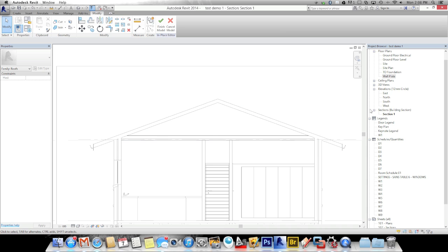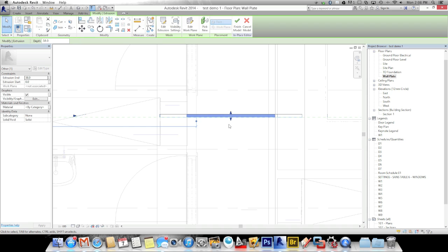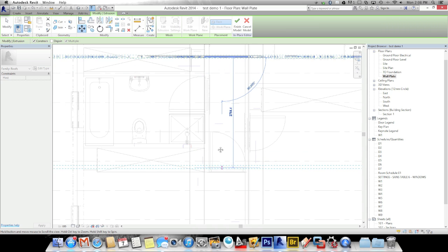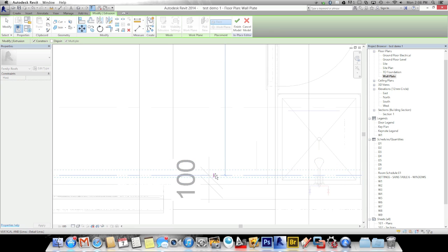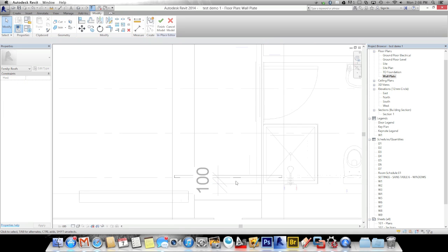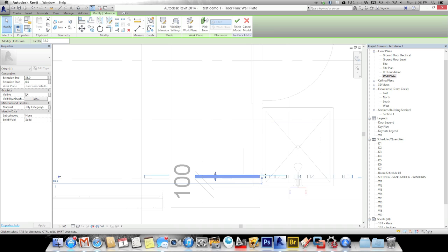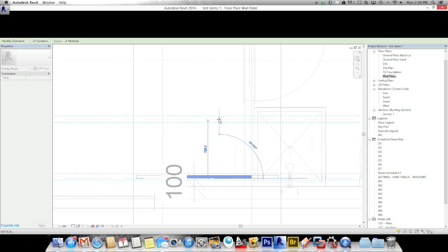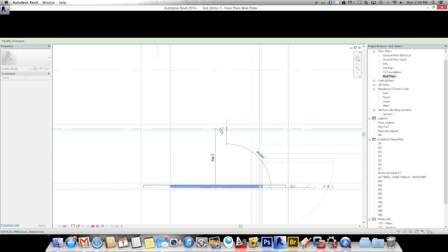Yes. What we're going to do now is go to wall plate, and then we're going to find the one we've just drawn, and we're going to say MV for move. And we're going to move it all the way down to there. Okay, so I'm not going to worry about centering too much now. I'm just going to go CO, copy, and I'm just going to copy them each to the lines that we've drawn for spacing.